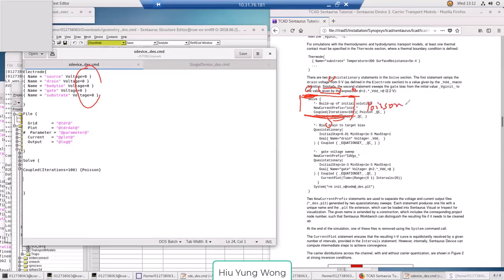It will be easier because for the current equation, the continuity equation, basically there should be a constant Fermi level. So it is very easy to include them later. So I will first solve a Poisson equation, and remember when I say solve the Poisson equation, I wrote this complicated 3D equation to you before, right? It actually is discretized into a matrix.